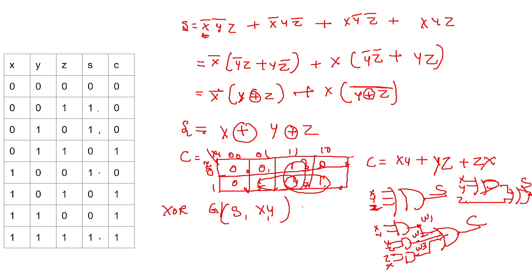So we can use 2-bit exclusive OR. Here again I need to define one more wire. So I will apply W4 as X Y. Again I will pass through one more exclusive OR gate, and then now the final S W4 is Z, and then